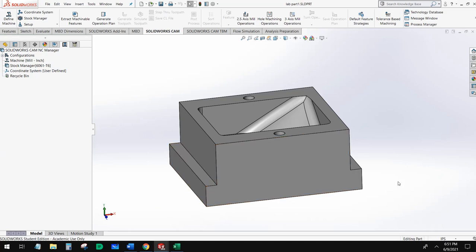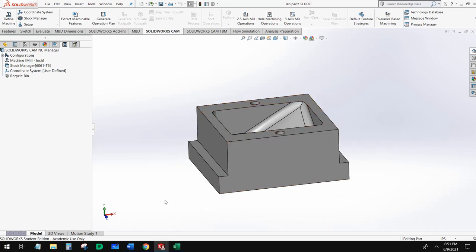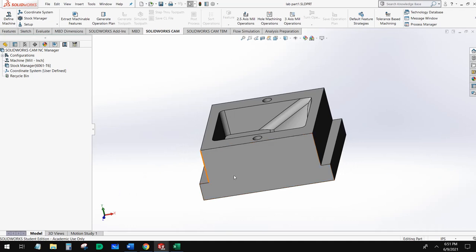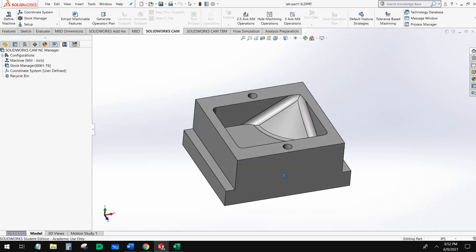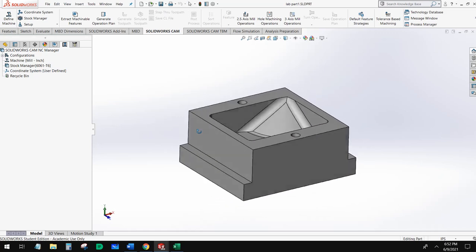And that's exactly what we've done here, is we've gone ahead and added this stock size in. So what this would be emblematic of is a stock size that we get. You know, we're buying stock, and when we buy stock, we don't always get it in the exact size that we need it. And sometimes it's not efficient to cut it down to the exact size that we need. Sometimes it's more efficient to machine it away from a larger piece, and that's what we're doing here. So what we have is 3.5 by 3, and we're going to machine this 3 by 3 cube out of it.